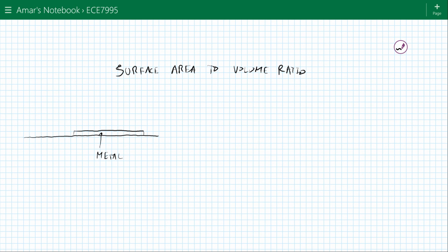In a lot of these types of sensors, the electrochemical sensors, for example, the sensitivity of the sensor depends on the surface area of your sensor. The larger the surface area, the more sensitive your sensor is. Why? Because let's say there are molecules in the solution like this. There's more area for the molecules to interact with your sensor. Okay. So one of the issues, if we take regular electrodes and make them smaller, is that the surface area of the sensor gets smaller, so the signal-to-noise ratio gets worse.